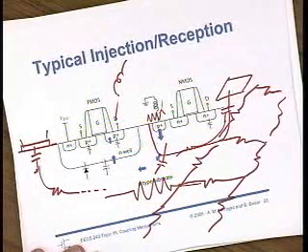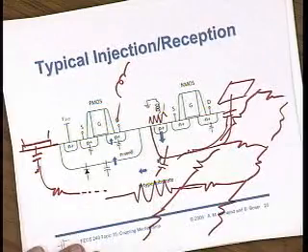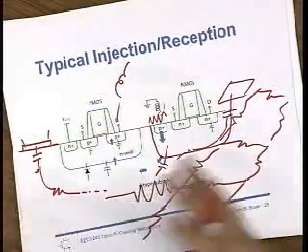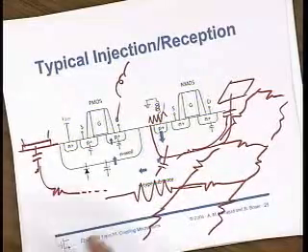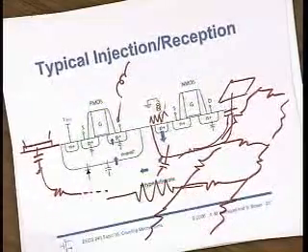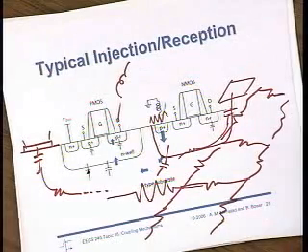Is there a take on, say I have a digital part and analog part on the chip, which one do you usually put in the extra well? Is there like a difference in doing so? Yeah, usually you would put your analog in the extra well because the extra well takes up more area. So if you want to design your digital circuits with the extra well, it automatically gets bigger, and you presumably have hundreds of thousands of gates. So you want to keep your digital as small as possible. So you could put all your digital in the substrate and then put your sensitive analog far away and in its own well to help things. If you want the maximum isolation, you put both in the triple well.